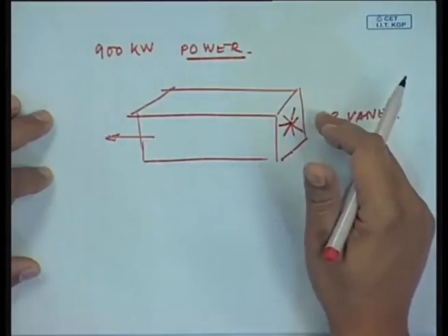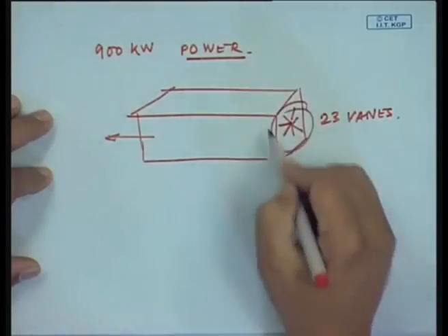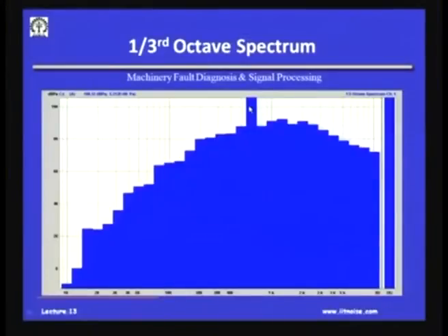So, this air gets sucked into the motor, and this motor is getting cooled, and this vane creates noise, because it is a fan rotating at very high speed. This is what is responsible for the motor noise, and this frequency has shown up here. And if there are 5 such motors in that plant, and there is a small variation in their speed, this is giving rise to beating. Obviously, I cannot bring down the beating phenomenon, because for operational reasons some of the fans rotate at slightly lesser speed than the other one. So, all I can do is to reduce the effect of the large noise which is heard because of the beating, by putting an enclosure on the motor.